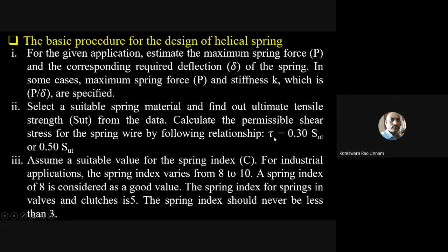Then once you determine that allowable shear stress, you need to assume a suitable value for the spring index. Like I already said, in case of static loading, you can take the spring index between 6 and 12. In case of dynamic loading, it is somewhat restricted to 8 to 10 only. Therefore, for most industrial applications, the spring index varies from 8 to 10.